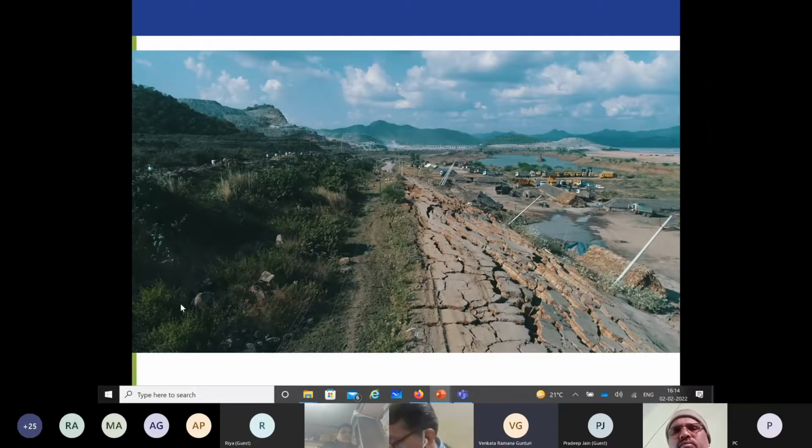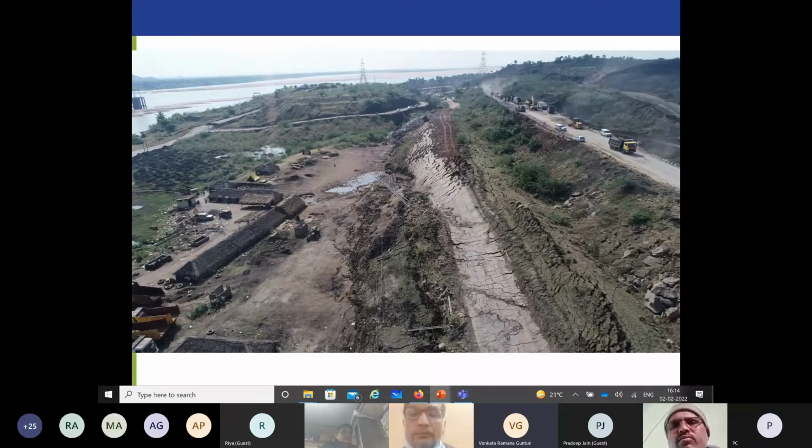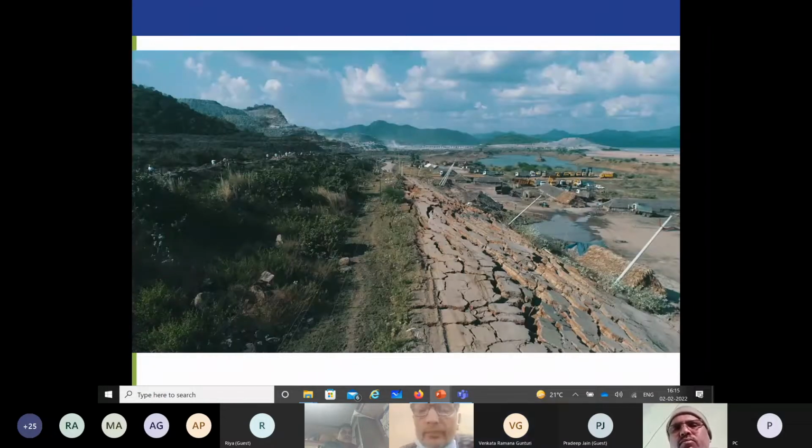This is not a video. I'll just show you, this is a static picture, and you can see here when they are excavating the dam, a lot of earthwork would be involved. They are starting to put it on the top. Okay, now because of this, since this is clay, you can see slippage occurring, slope failures are occurring. You can see here, this is a road, and this pavement, all the stuff has come down, and a severe amount of distress is observed. You can see here very clearly large cracks and downslope movement.